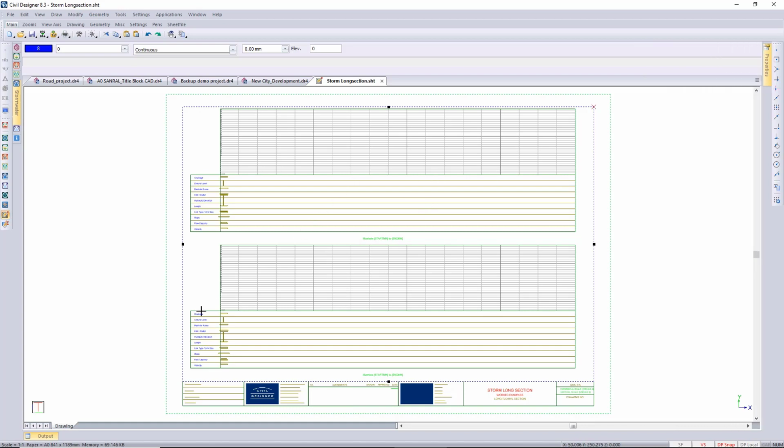That coordinate system, if you're trying to figure out where you are, you can always just do a coordinate jump, even in the sheet file editor. So I'm just using the U shortcut key. I'm going to type in 0 x and then 65 y and enter. And just look where the x is down at the bottom if I press the highlighting of the coordinate position.